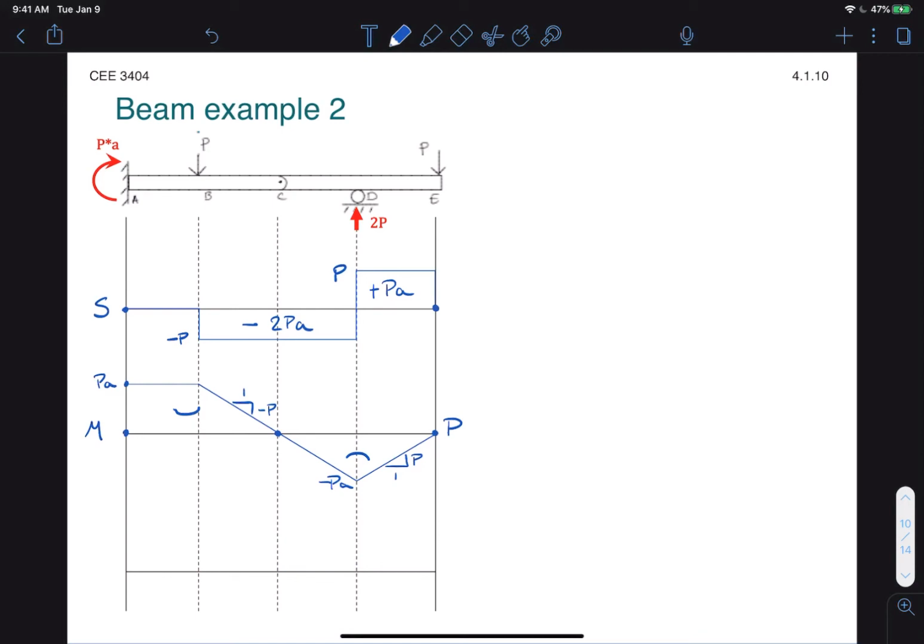So let's look at the supports first. We know that the roller at D doesn't experience any lateral forces, so it should stay put at that point. Obviously it cannot move up or down as well, so we know that the deflection diagram must go through that point. We also know that the beam must leave the left side at a right angle because it is fixed. So the only way to maintain positive curvature by leaving at a right angle here is to curve up, like so. It's just not possible for a cantilever beam to have a positive curvature and curve down.